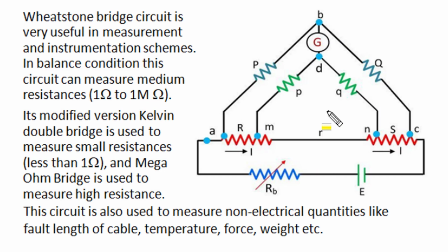A modified version of the Wheatstone bridge has two ratio arms. Capital P and capital Q is one ratio arm and the second is small p and small q. Such bridges are known as the Kelvin double bridge, and they are used to measure small values of resistance which are less than 1 ohm, and during such measurement we can eliminate error caused by connection wire and contact resistance.